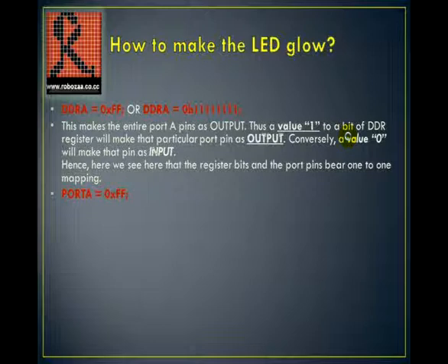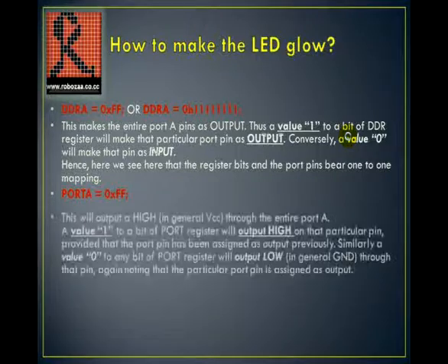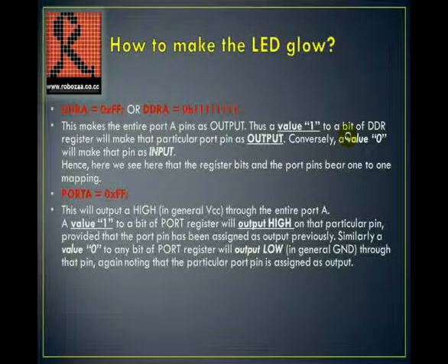Now that we want to make our LED glow, we have to give a high output onto the port pin because we made the connection in such a manner. For that we'll use PORT A equals 0xFF.